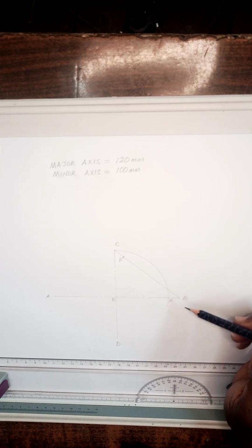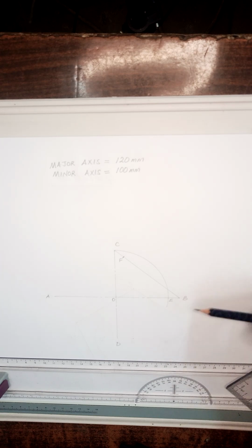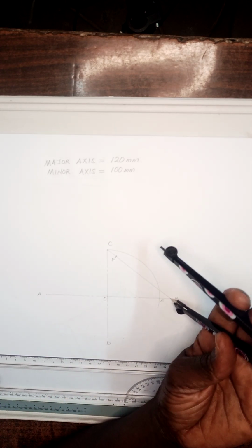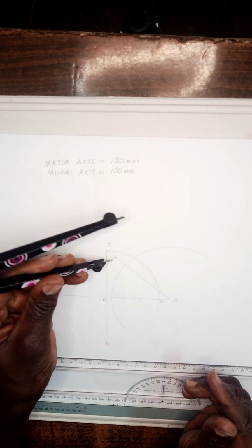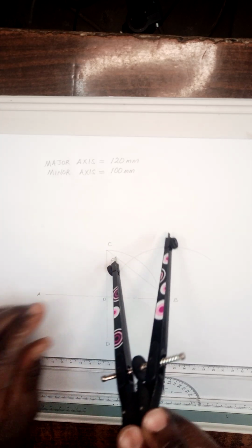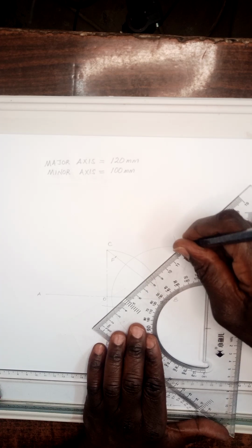We are now going to use point BF, or line BF, and bisect it. How do you bisect that straight line? So you get point B to more than half of line BF, strike an arc like that. Okay, then go to F, you do the same. Next, we draw the perpendicular bisector of line BF.